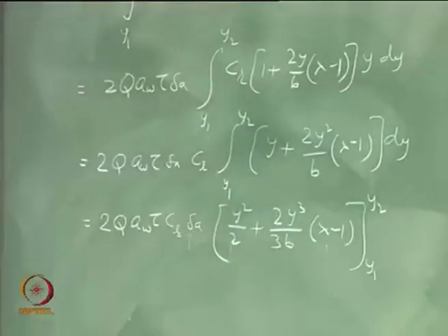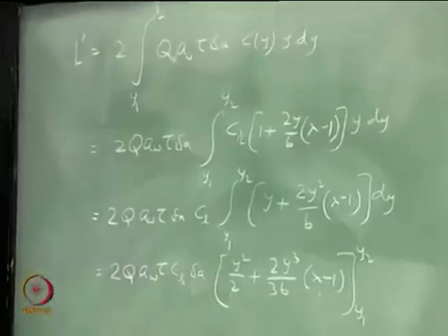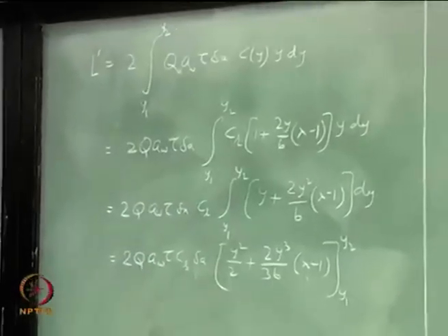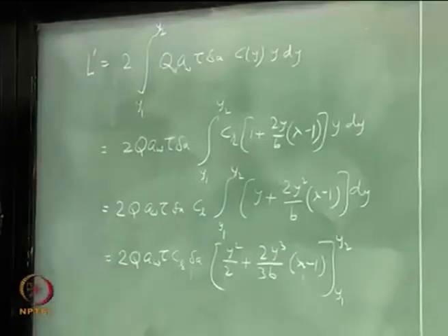Now, I have to non-dimensionalize everything, because I want to find out change in rolling moment coefficient because of the aileron deflection, and that has to be done with respect to the wing.